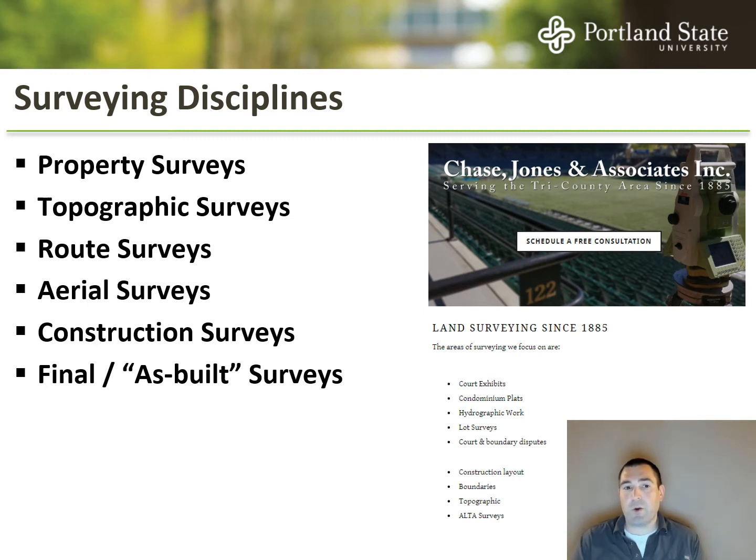So the surveyor would go out and verify whichever values we asked them to, and then we would have an as-built set of plans. So maybe they cross out the 50.25 and say, hey, this is actually 50.28 feet wide, if we want them to be that precise. And those are really important from an inventory and documentation standpoint. If we need to do service to that bridge down the road, if we have any questions, if there is a structural issue with it, having the true dimensions is really important.